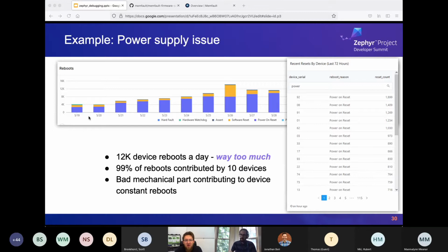Meaning that tracing an issue like this, you can then roll out an upgrade which, say, immediately goes to deep low power sleep when the device boots, or if the reboot counter is higher than some number, you sleep, say, for an hour and then try to do something useful. So you can conserve battery and really force the device into a more reasonable operating mode, circumventing some hardware issues that may be in place.